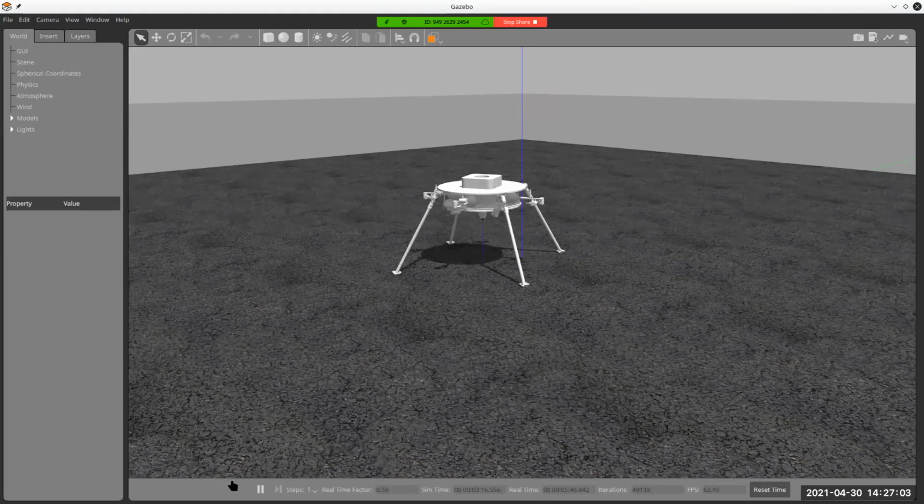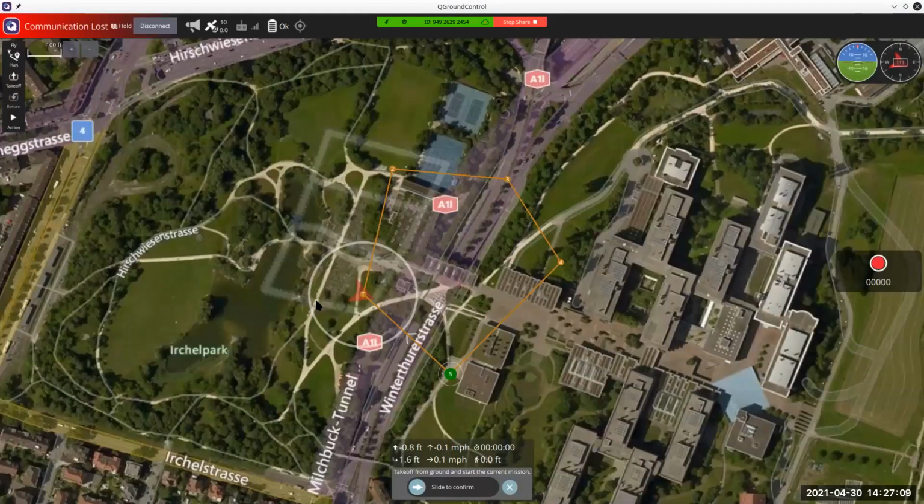It was actually good that it was unstable because it showed that. QGroundControl is a methodology by which you can engage and fly the vehicle through some basic pattern that begins to give you some idea about how your navigation algorithms are operating. And it's not so much navigation as it is, do you have stability in the ACS system, or is your thrust vector control system working well? It's cool to see very quickly does it follow the pattern, or in our case, does it start to rotate in yaw a little bit crazy and then go off normal? So that's great.